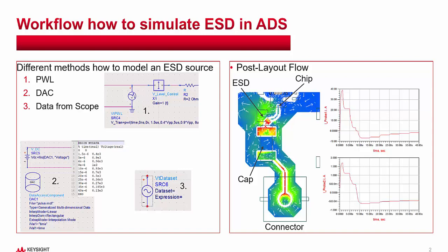It is also very important to have accurate models for other components, such as capacitors, ESD diodes, the chip input impedance, and probably the connector impedance and active devices and all other passive devices. Many vendors provide an ADS design kit or model library for their components. It is also possible to import SPICE models in different formats, such as PSPICE, SPICE 2G, SPICE 3, AT-SPICE, Spectre or HSPICE.